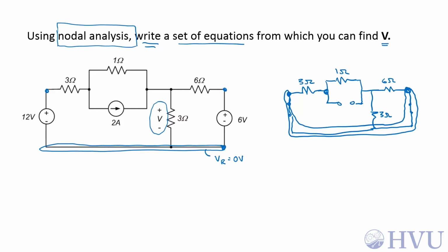There's also an independent voltage here. I can have a voltage difference between here and any adjacent node, and an independent node here, since I can have a voltage difference between that and any of my other nodes. So let's call this VA and this node here VB.